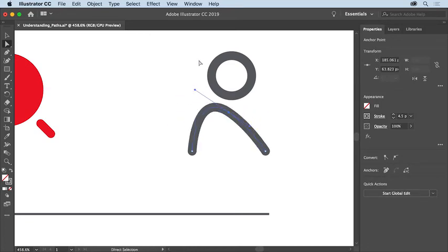The last type of path you'll look at are shapes. A shape, like a circle or a square, is a closed path, since the starting and ending points of the path are the same. In other words, all the anchor points are connected one to another in the shape. With the Direct Selection tool selected, click the edge of this circle shape to select it. You should see 4 anchor points that control the curve of the path. Move the pointer over one of the anchor points and then click to select it. You'll see the direction handles that control the curve. Try dragging this anchor point to move it. Then drag the end of a direction handle and you'll see that the curve of the path changes.